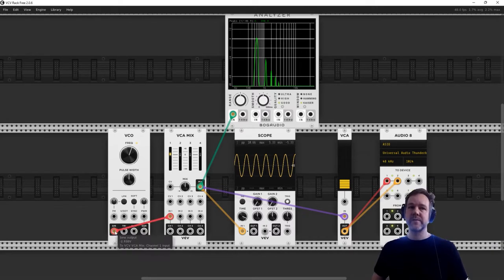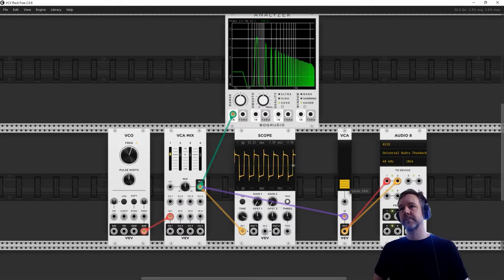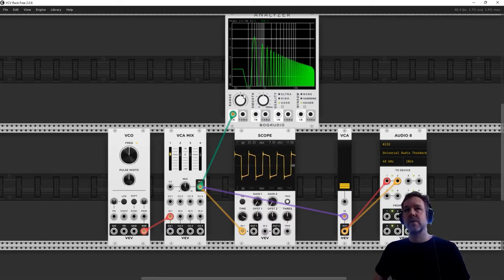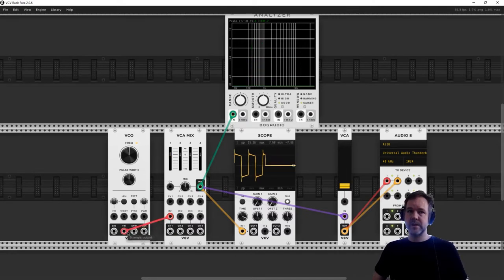Now, another sound wave, if I drag this out and put it into square, you're getting a very different sound. You're getting a lot more harmonics. And these are all sort of partial tones. These harmonics occur in whole odd number multiples of the fundamental frequency, whatever this first one is here. And if I jump to my triangle, it's kind of a mixture of the sine wave and the square wave.